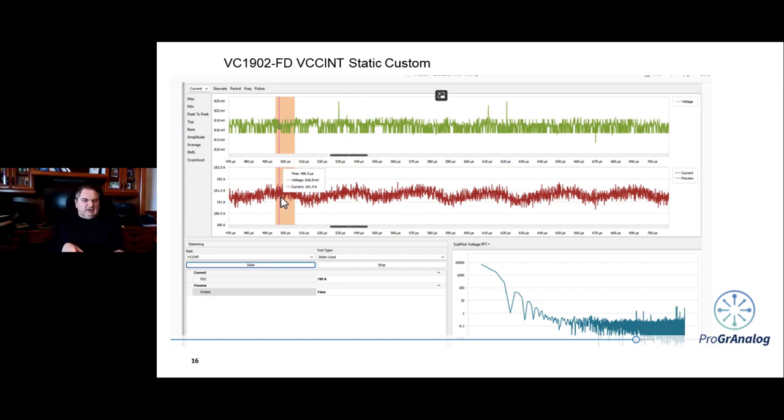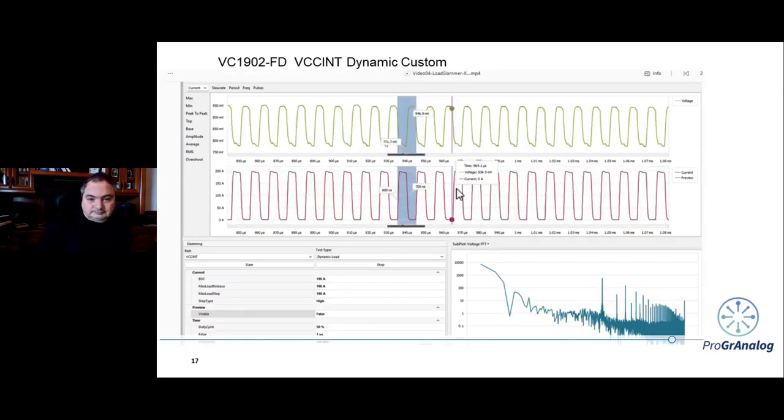And you can see, I think on the left-hand side, Rob alluded to, you can choose min, max, and the usual kind of data capture options you need in a piece of test and measurement equipment. This is when we're doing a duty cycle sweep. And remember how you have to capture a lot of pulses, repetitive pulses, to find a weakness, or the weak point of a regulator.